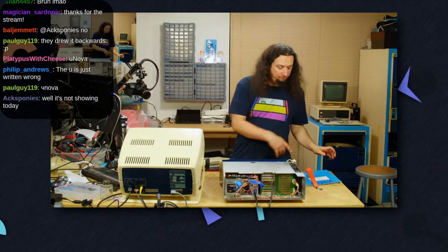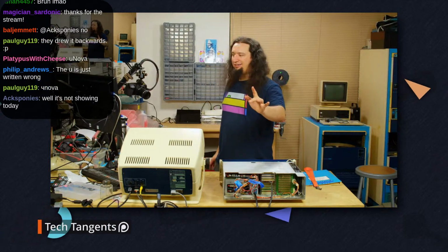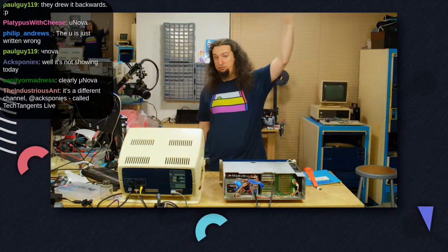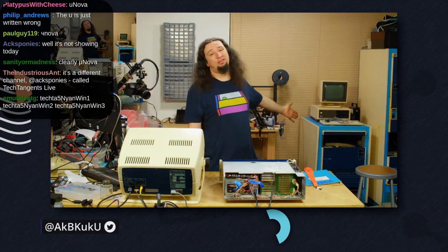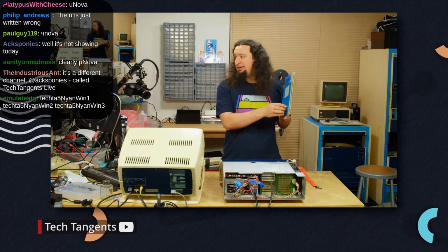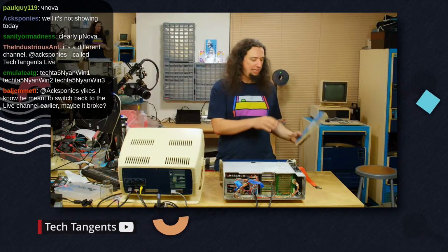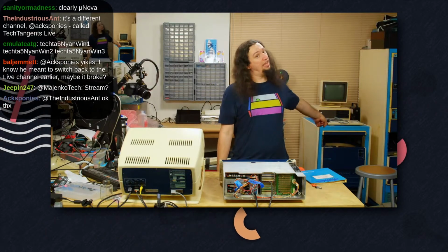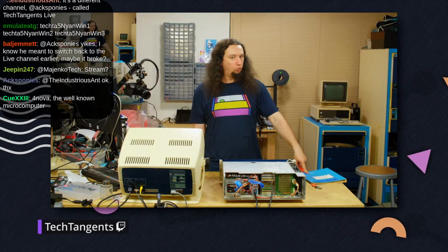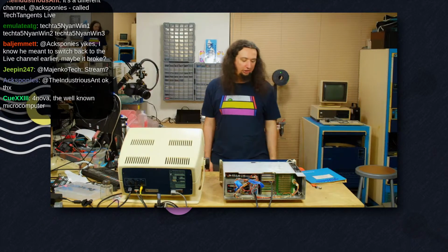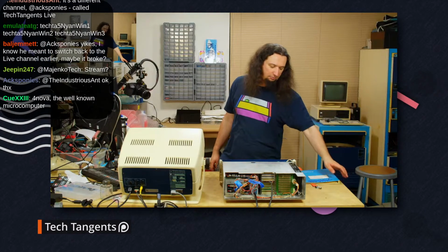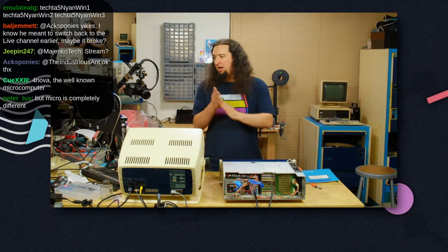There is still a possibility that the async controller card that has the disk interface stuff is providing a ROM that is doing something weird with the memory. I don't know, and it may need one of the disk units working to be able to boot. I don't know, because again, we have an 8-inch floppy disk labeled boot right here, has not been imaged and will not be going in that drive until it is imaged, because that's possibly the only floppy disk known to exist for a Data General microNOVA. So we will be imaging that. However, it is hard sectored, so imaging it is not trivial, and I need to put some time into that too. So there are a lot of avenues to pursue here.